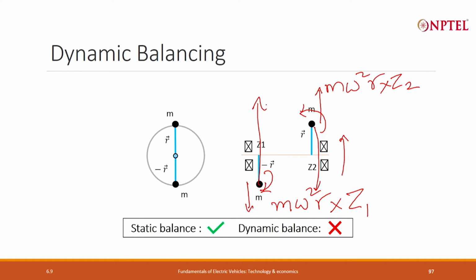moment. So, what will happen is that the shaft during the course of its revolution is banging this way, this way, this way in different directions and taking up all the little clearances in the bearing, and that will cause a noise.